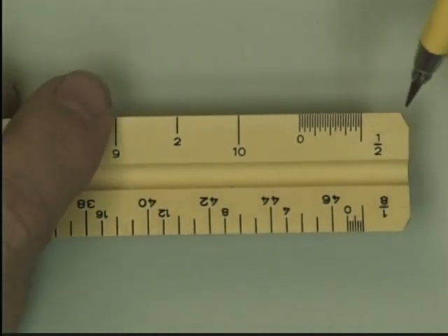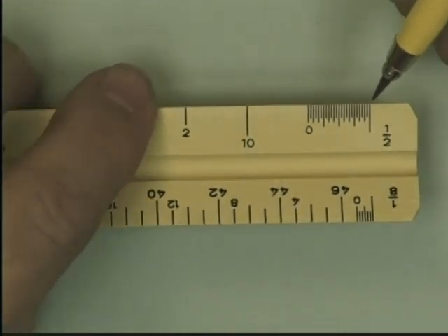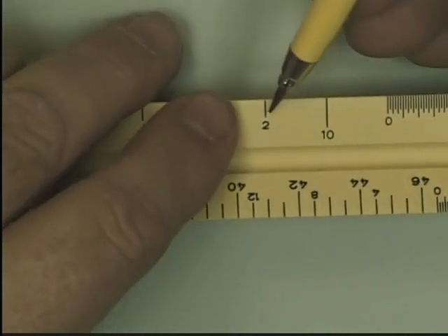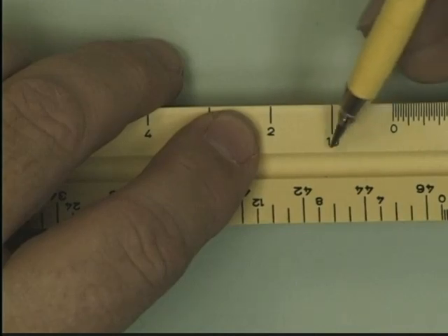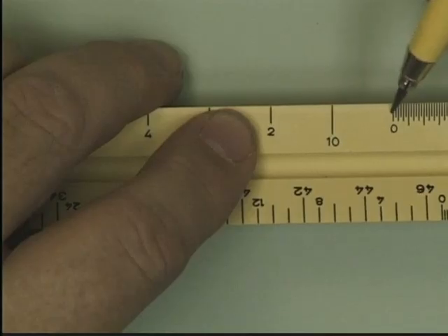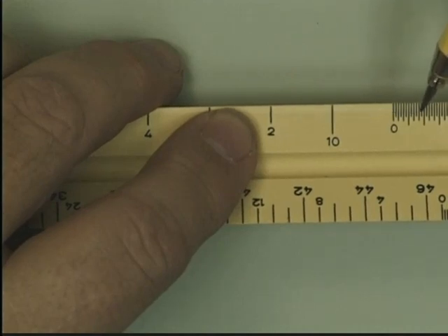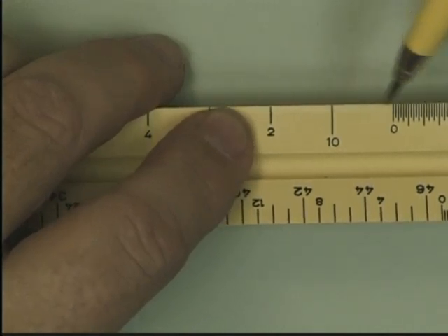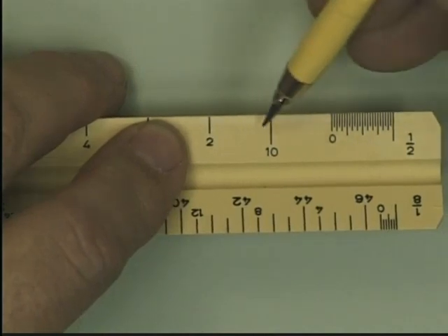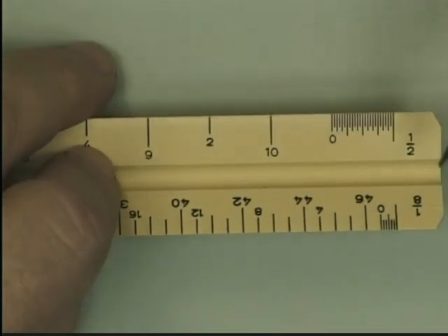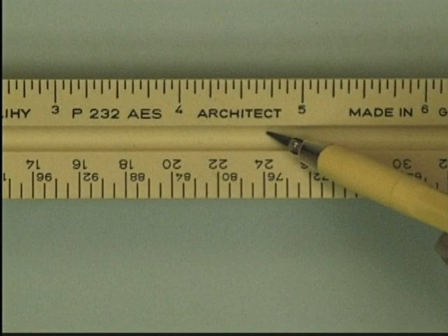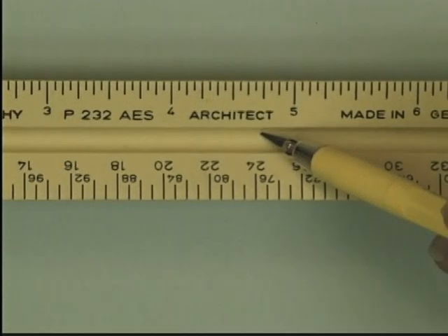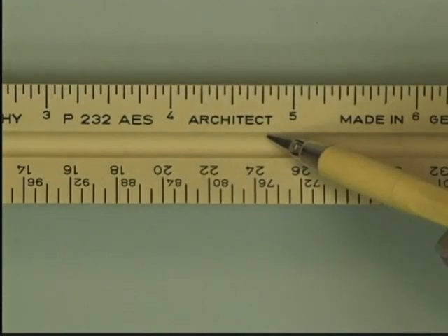What if I wanted to measure 2 feet 3 inches? Well, here's the number 2. Here's 2 feet. This is 1 foot. 10 is coming the other way. Plus from the 0 over, it would be 2 feet 0 inches, 2 feet 3, 6, 9. So this is divided into 12 parts for dividing feet and inches. That's the 1/2 inch equals a foot scale on an architect scale. And somewhere on the scale, it will tell you whether it's an architect scale or not.